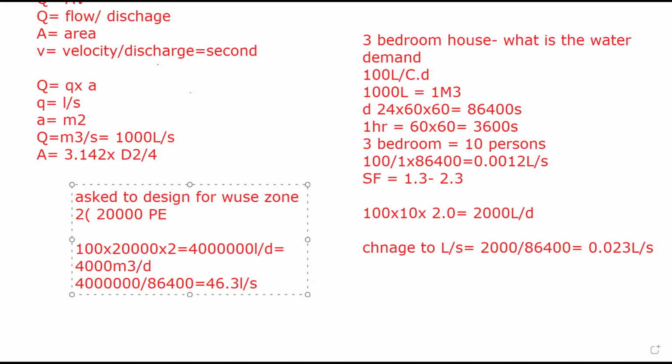In this chart, you need to input parameters. Remember those 4 parameters I told you about? If you give it 2 parameters, it will give you out the other 2 parameters, then you go to your detailing. On the diagonal are the pipe sizes. Look at this: this is 1,000 mm, this is 900, this is 800, this is 600, and so on and so forth.